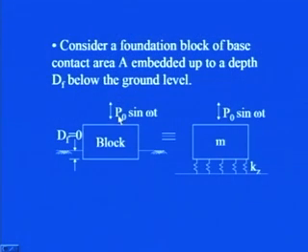And then this block is subjected to this force, that is P naught sin omega t. So, this is the physical system: this is the soil which is lying here, and with some embedment depth the block is being casted, which is subjected to the external force P naught sin omega t. Now, as I told you, this soil can be modeled as springs, a series of springs.